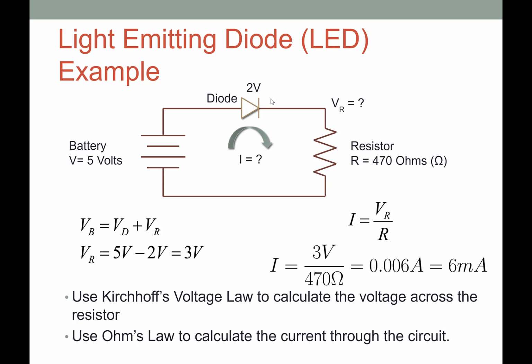So we need to calculate to see what kind of current we'll be sending through our circuit. Our supply on our Arduino is 5 volts, so that's why we've used 5 volts here. And you've been given resistors, one of which is a 470 ohm resistor. The current that a light emitting diode likes to run at is about 10 milliamps, so we can go through the calculations to make sure that we're not exceeding that. Above 20 milliamps, that diode will die and no longer work.